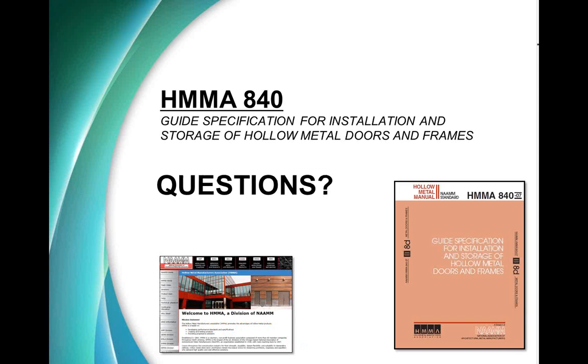It all depends on manufacturer and expertise of the welder. There's a lot of setup as far as on a weld table to square the frame and brace it and everything like that. So I'm not sure how much of that is considered into the frame or the welding. Different manufacturers have different times based on their design. And I would say a frame should be able to be welded within probably, depending on the welder, the expertise, anywhere from like 15 minutes to an hour.